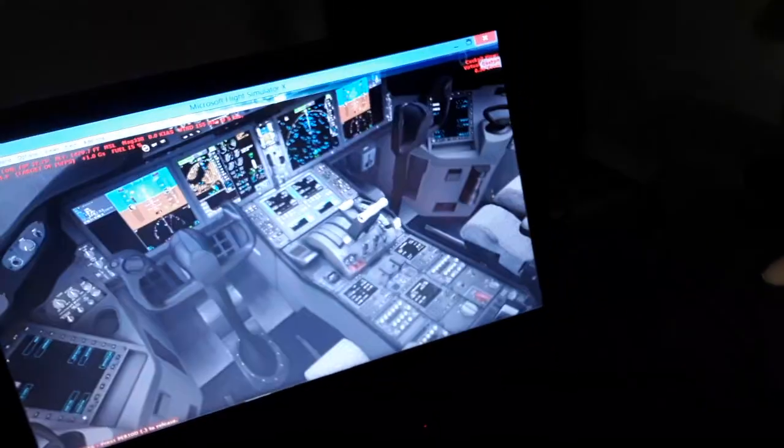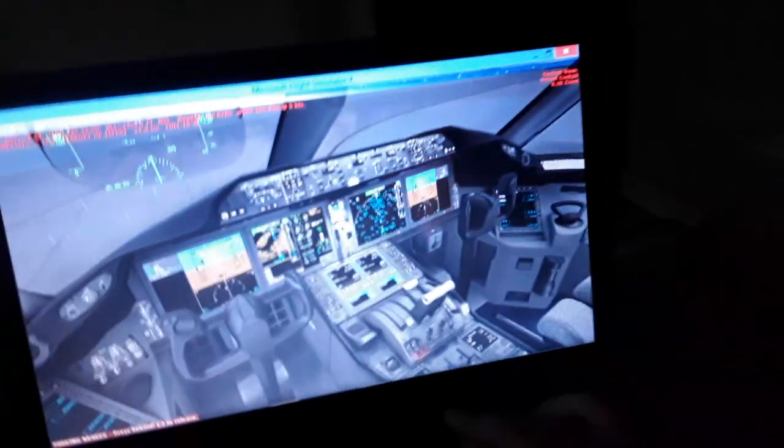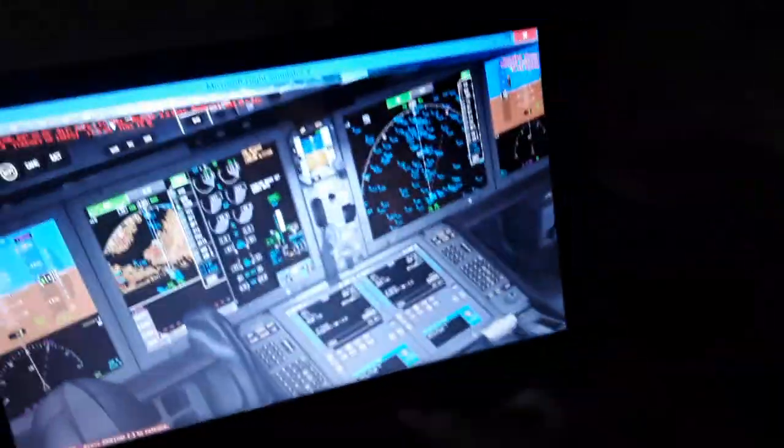So also, as I'm going to talk later about the systems, I have to show you now the flight controls. I will show you a bit more of the flight controls of the Boeing 787 right now. I will show you also the horizontal trim stabilizer of the elevator. Also, we have the automatic trim of the aircraft, and this is a fly-by-wire aircraft. It has its flight control computers. I will show you right now. You can control all the flight controls in flight in normal, alternate, and direct mode, like in the Airbus aircraft.